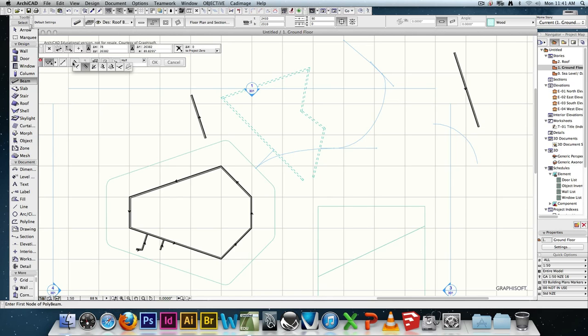Now, what else can we do in there? Okay, here's a good one. See this guy here? What that one does is I can draw a beam that is half the angle of this and this. So I can click on that one, and now if I draw a beam, it is half the angle of this and this. This is very important when dealing with slopes. If they're at the same angle, the joining point of those two sloping surfaces will always be half the angle. A classic example: at 90 degrees, it's 45 degrees that those two slopes will meet.